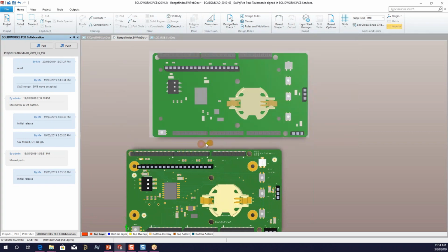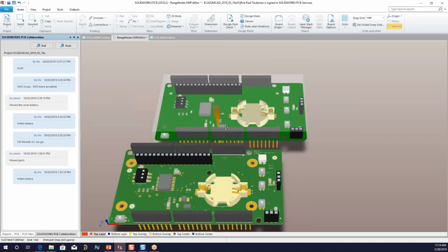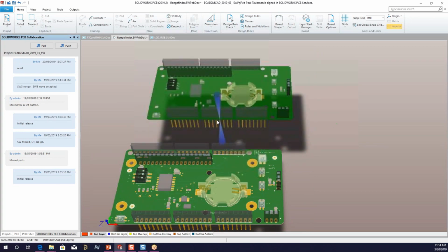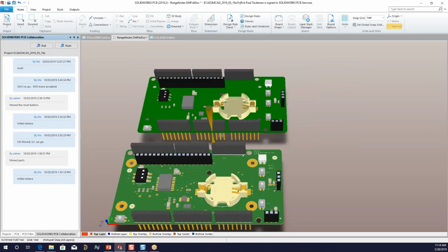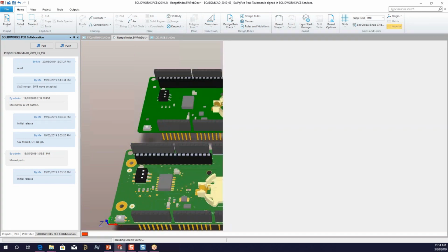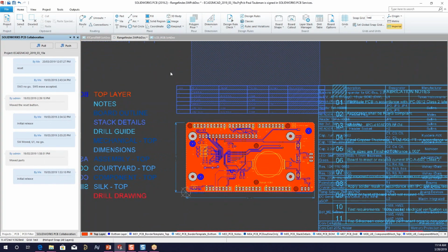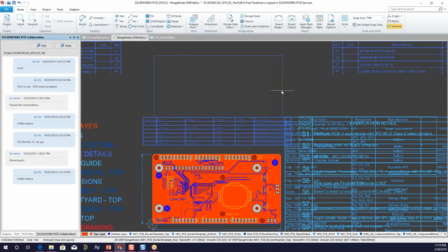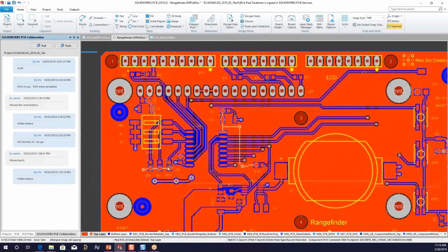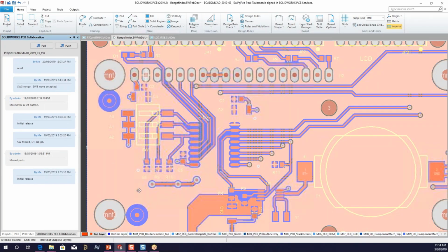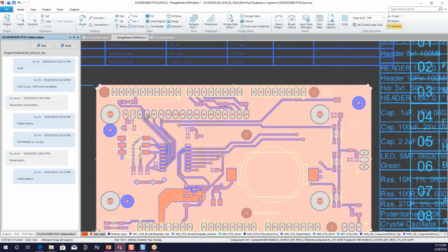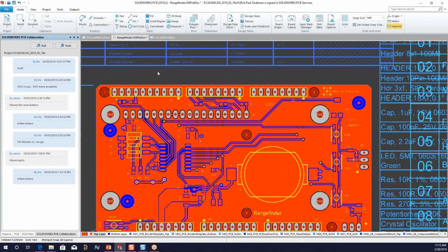So here, as I mentioned before, this is the board itself. So yeah, it looks the exact same, but the difference is that I can take parts in the real board and move those around, as opposed to this here, which is just simply a blob of a representation. As a matter of fact, if we go to the 2D view, and this is the view that we tend to work in about 95% of the time in a layout tool, you can see it's just a box here, just representing what they call a 3D body, as opposed to what you see over here where we actually have components, and we've got our layout, our copper pour, our traces, and all the other primitives that are associated with this particular board over here.